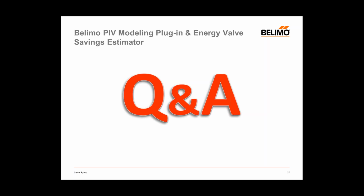When do you use Trace versus eQuest? Trace 700 versus eQuest is really a matter of the customer's choice. If the customer uses more Trane equipment, possibly, they would license Trace 700 from Trane. If they don't, they can get the eQuest tool from the Department of Energy, and that is a download that's available for free from the DOE website.